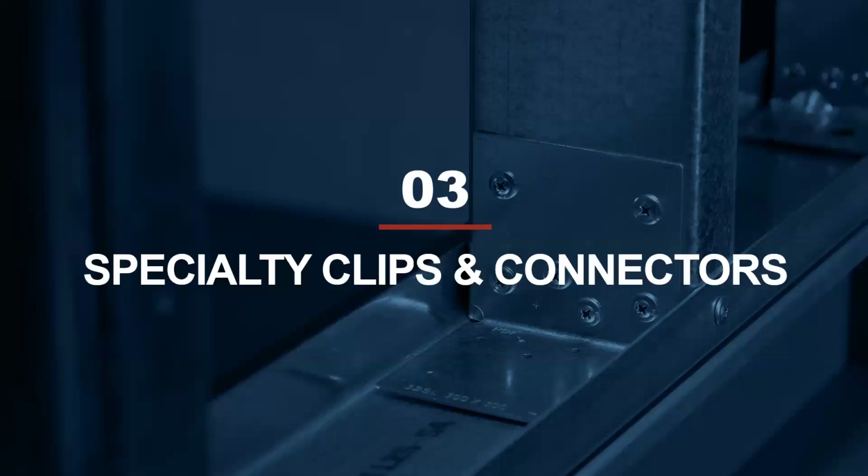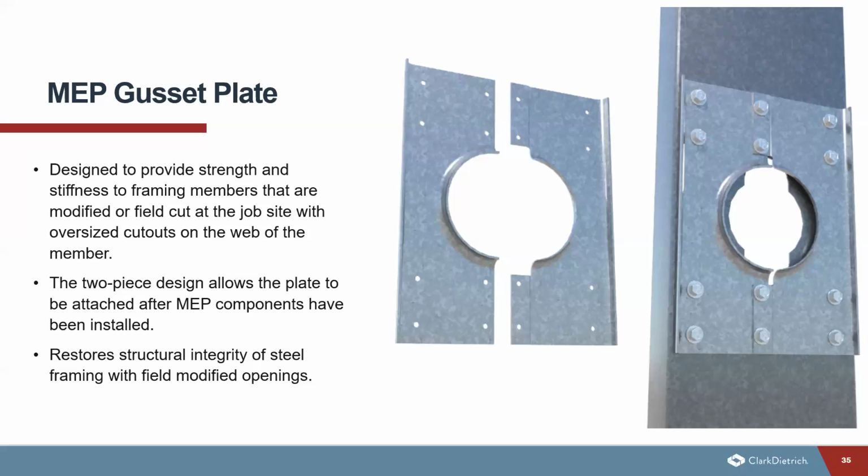So moving on to some of the specialty clips and connectors that are on the market. One of the newest ones on the market is a gusset plate that's going to be designed to help the MEP components pass through after it's been repaired. So essentially, if a stud knockout is changed or cut in any way, it loses its strength and stiffness, and it's typically not allowed by IBC. However, there is a quick fix now that can be used, and it's a 2-piece gusset plate. You would install this over top of the knockout and use the provided screws to install it. Again, it's going to restore that structural integrity of the steel framing or any field modified opening.